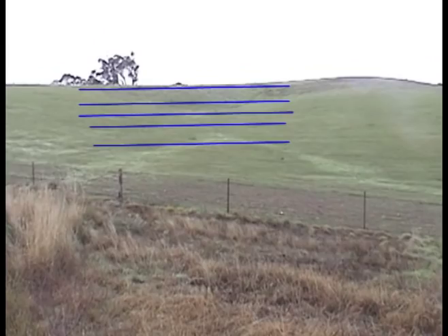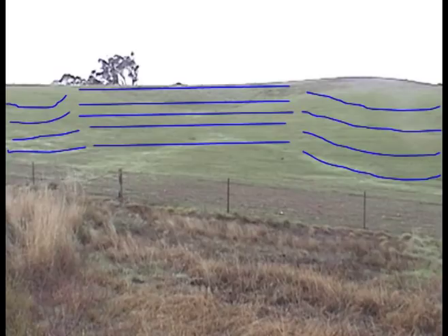Okay, got it? Then what we're going to do is start out here and find the lowest ridge and start going parallel up. This is a simple, by-the-book keyline layout. There it is. From the key point, parallel down, lowest reference contour on the ridges, parallel up. The water will naturally start to migrate towards the ridge in many cases.